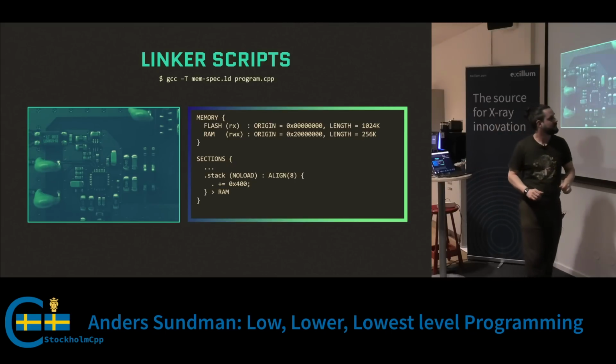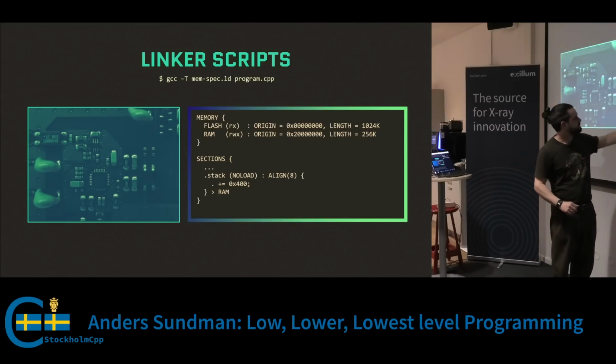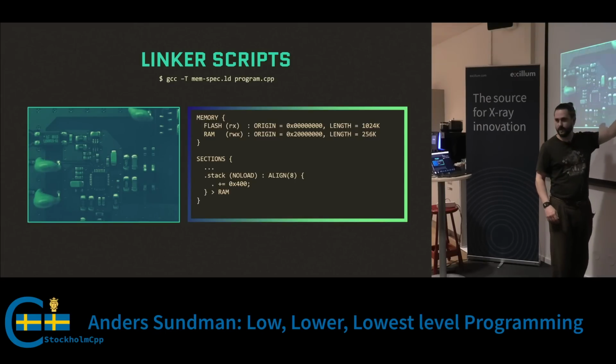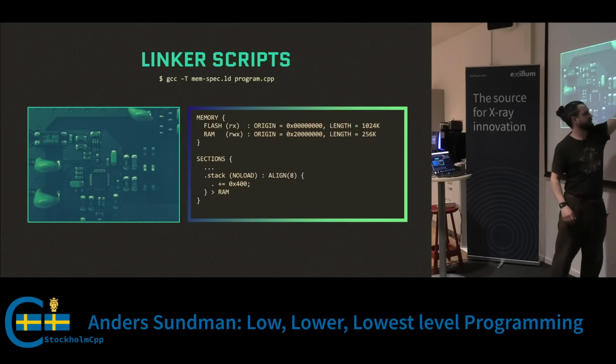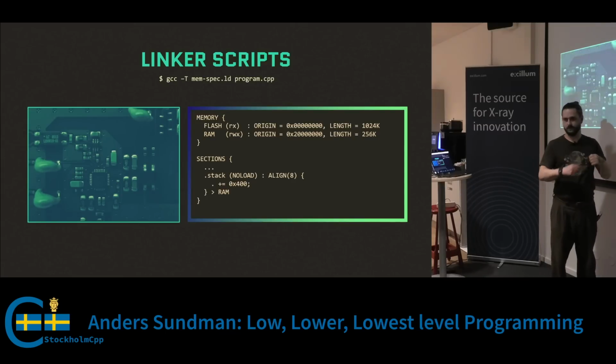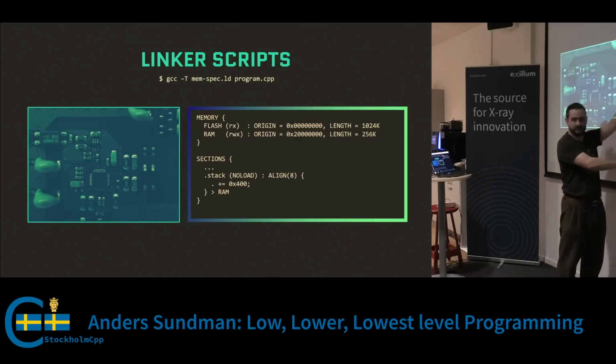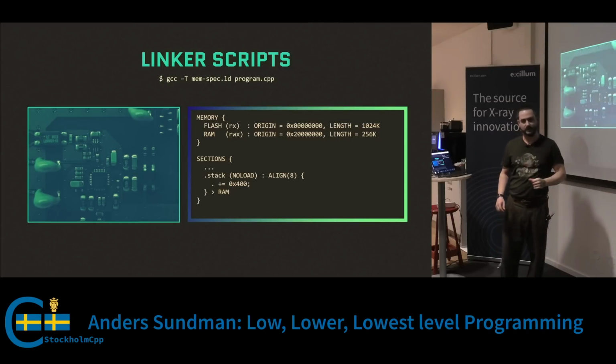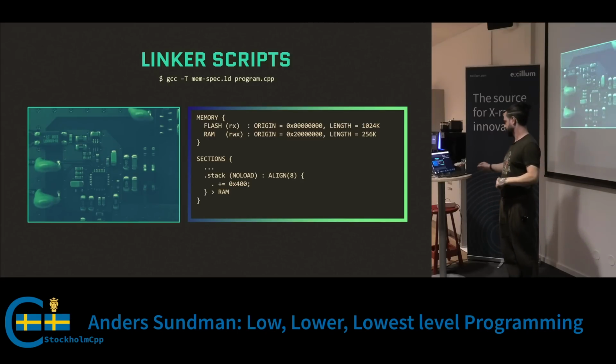Stack is a special thing you can specify. It's not actually so special. This dot here is like a running counter of how far you've gotten in your memory. So if you have a lot of sections up here, then the dot will tell you this is how far my address counter is. And if you add to it, you will just carve out a big chunk, and then you add that to RAM. So you just have a big chunk of stack here. And you might need to align it a little bit more than the other segments sometimes.